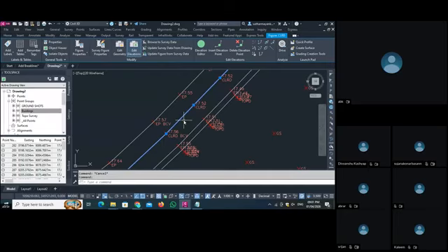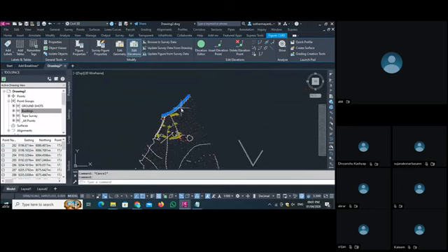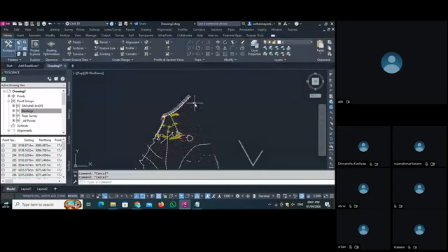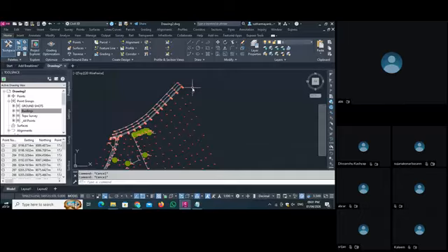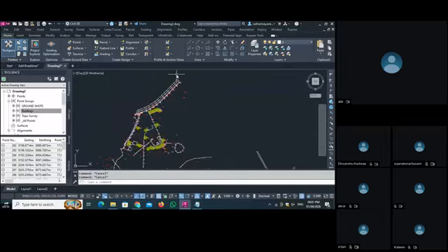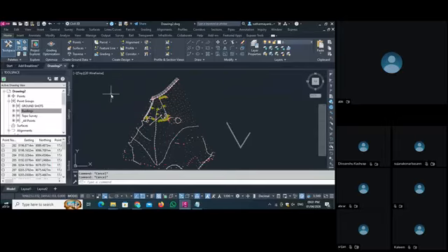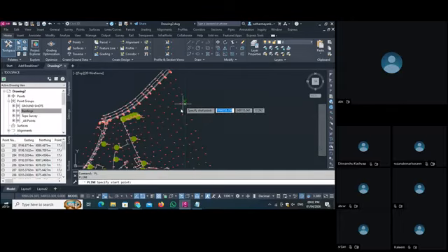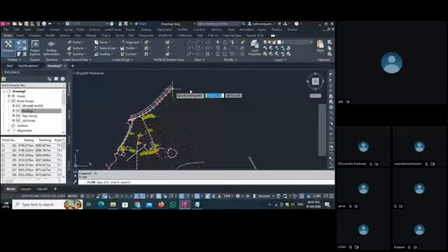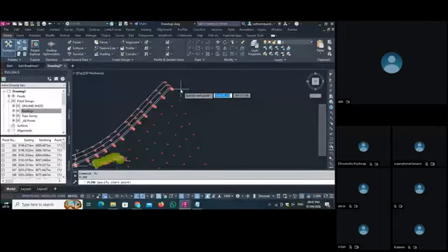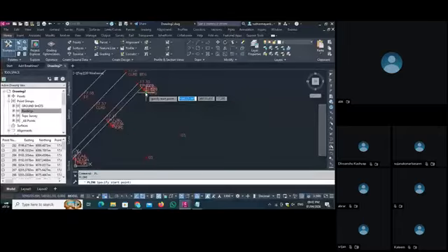For a boundary, road and a boundary, we can create a boundary line and all those things with the help of a polyline, and then we convert that polyline into this 3D feature line. Like if I show you, if I set a polyline here, and if I want to set a boundary, because when we are doing our initial work, we have to set the boundary of the project.